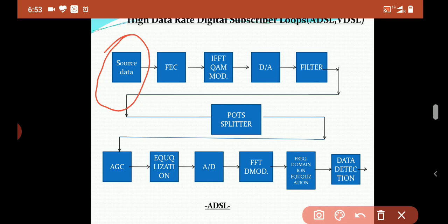It is a pseudo random sequence generator which provides a prescribed sequence for characterizing the channel during a training period. Characteristics of the channel determined during training are: first, attenuation and phase distortion across the band; second, noise interference level; and third, information capacity of individual subchannels.